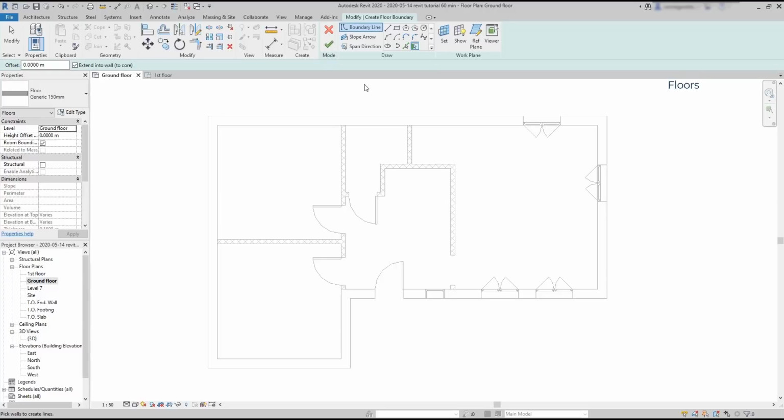But let's proceed. To draw a floor, it uses by default the boundary line, and to make it, I can use a line, rectangle, arc, among other geometries, or this last one, which is currently the selected one, called Pick Walls. I'm going to choose it, and you will see that it's actually very simple. I only need to click on the walls until I reach a closed boundary.